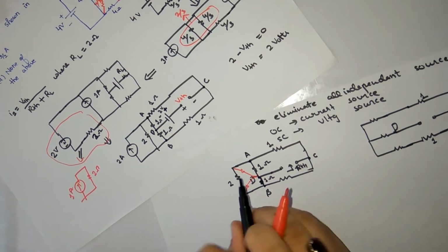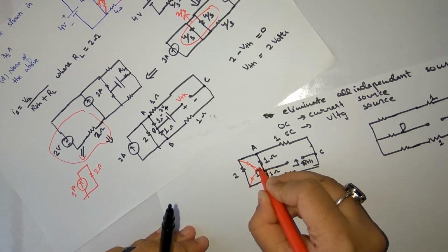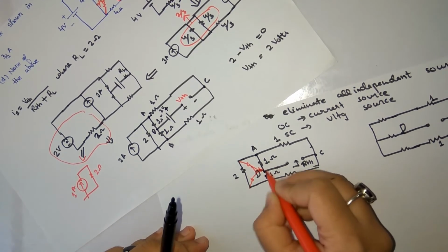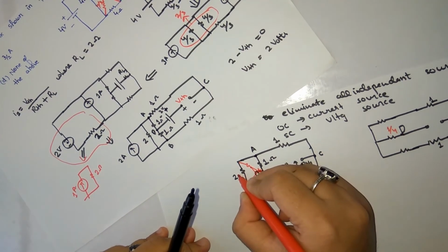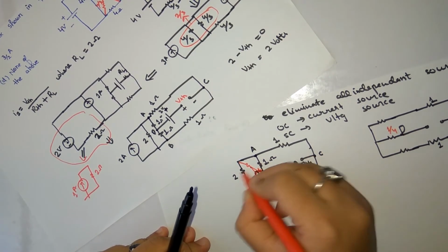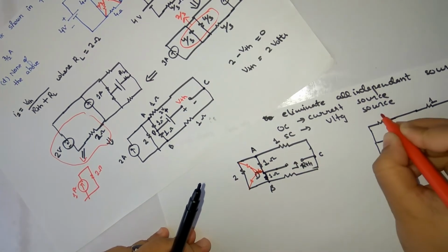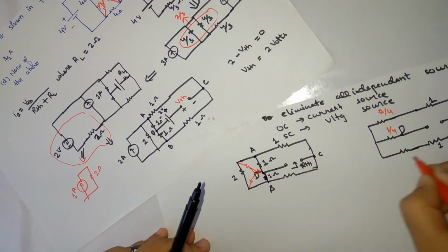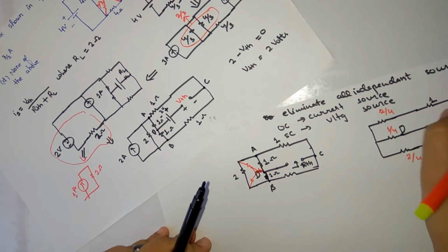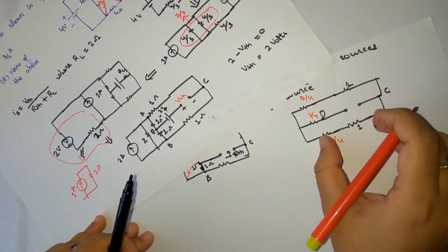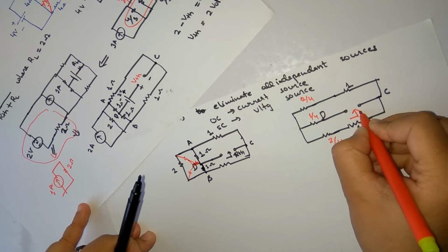Now what will be the value of this resistance? Over here there will be a resistance. So this resistance will be 1 into 1 upon 4. So this is 1 by 4. This is 2 into 1, between these two branches. So 2 into 1, 2 by 4. This is also 2 by 4, and this is 1. So these two resistances we can make out are in series, and we have to calculate RTH along this.